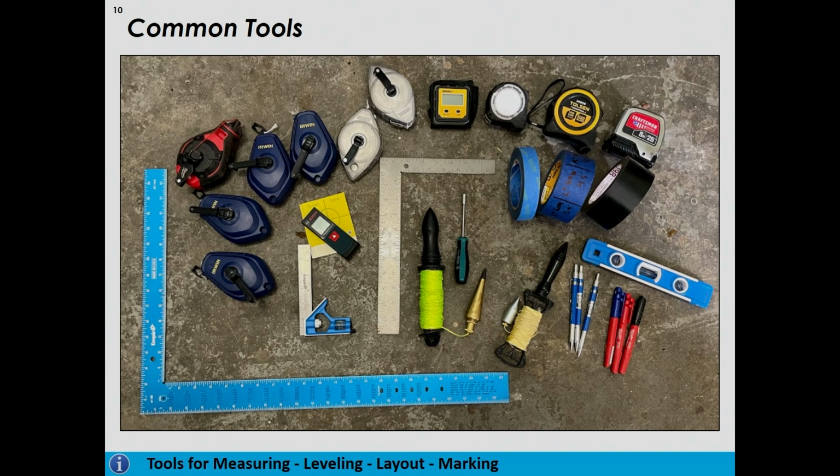So this is at the very basics. We would have to be using a plumb bob, a string or a chalk line, and a series of markers to establish this. This would be the more mechanical method, if you will. If we're using some of the newer systems out, or if we want to get some of the tooling ourselves on an individual basis, we're probably going to be using a series of lasers now. We'll still use the plumb bob to establish our drop points front and rear, and then we're going to shoot a laser to get our straight line over there.